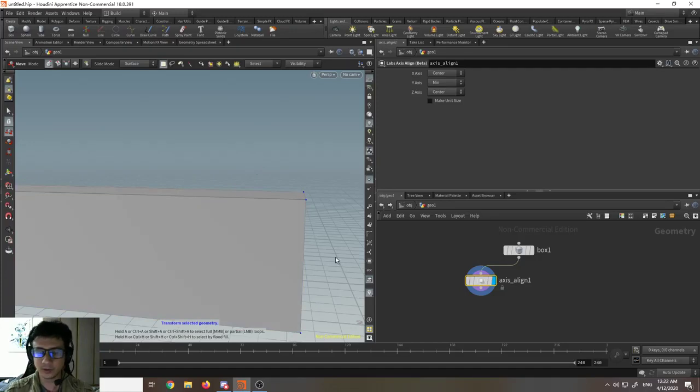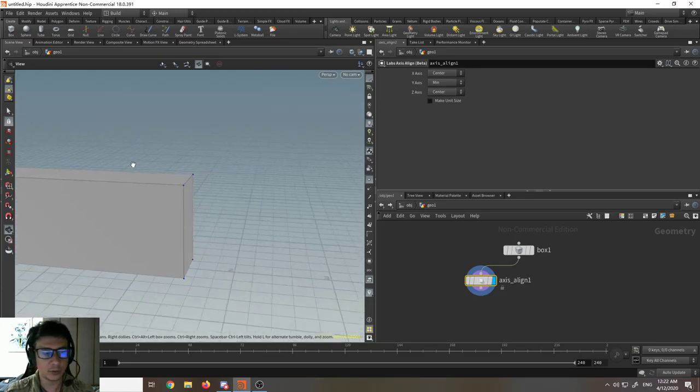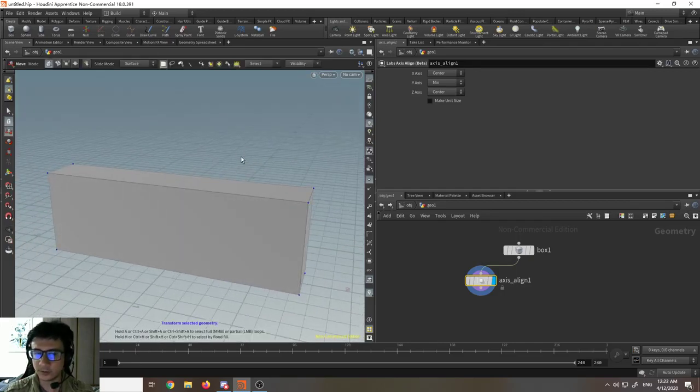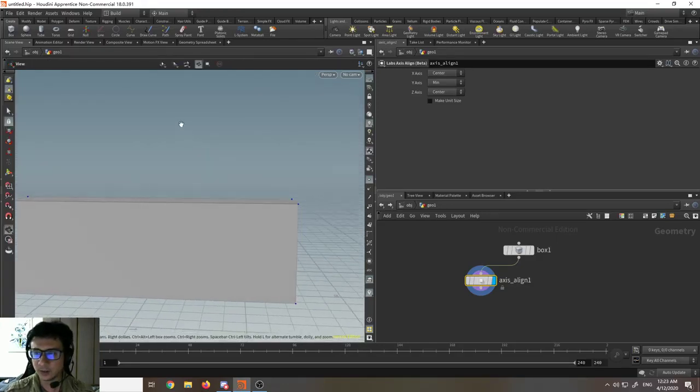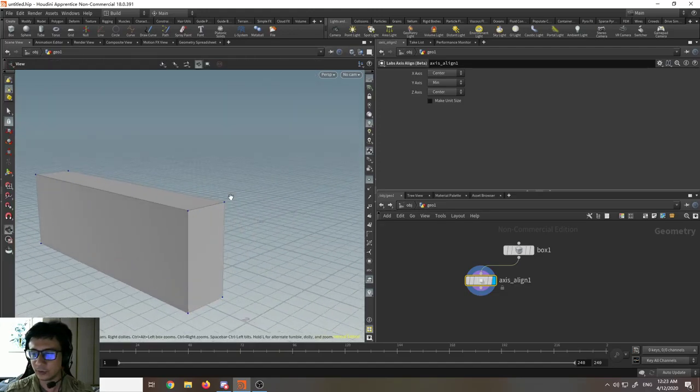I want to destroy it, and normally in Max or in Maya or in Blender you may use a boolean, you may need to cut, and it's a very destructive workflow, because once you cut the mesh you better have a backup of it. And if you cut it wrong, then you need to cut it again, and cutting meshes is not the most exciting thing to do. So what we're going to do is use a spline here, and we are going to create a destroyed wall.